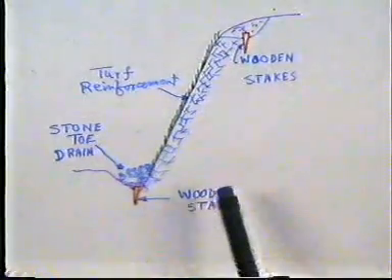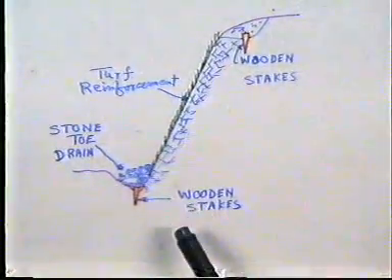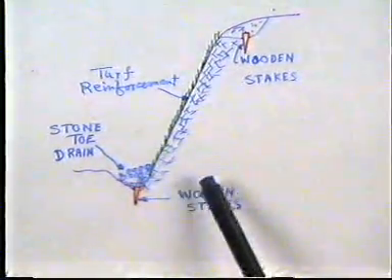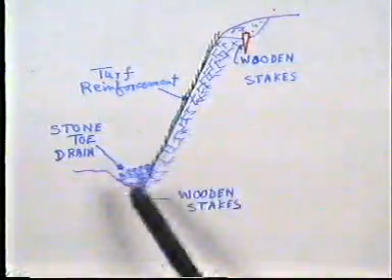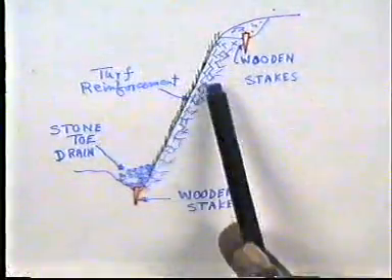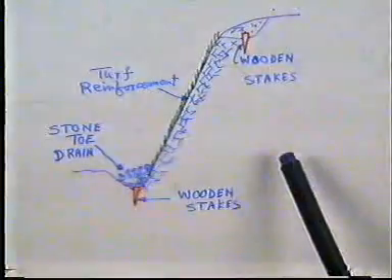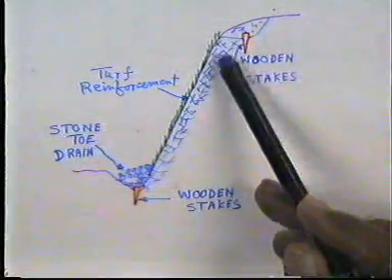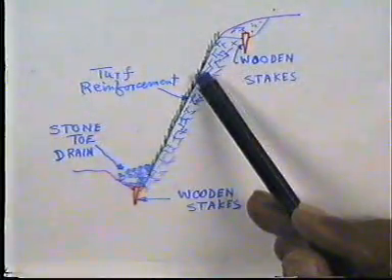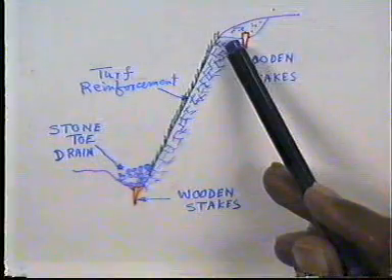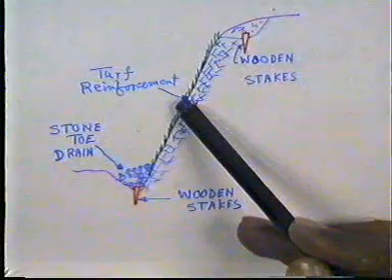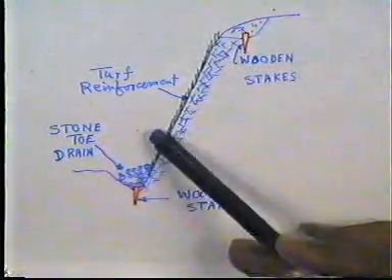Initial erosion was resisted by the strength and subsequent membrane action. As the jute or the coir biodegraded, the roots of grass and vegetation reinforce the surface to protect it permanently from the wind erosion.